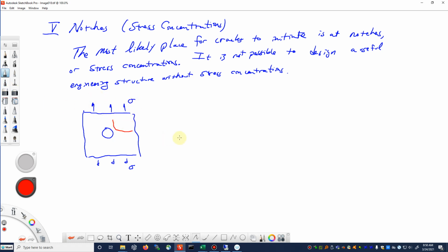or the remote stress. If you've taken a class in theory of elasticity, you've probably gone through the derivation of how the stress concentration factor is defined as the maximum stress divided by the nominal stress for a plate with a hole is about 3.